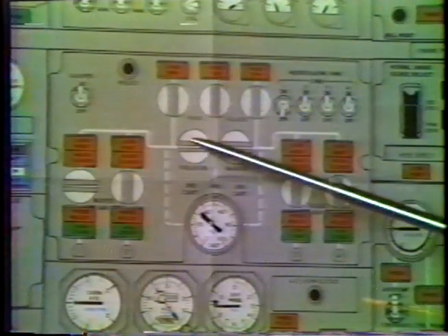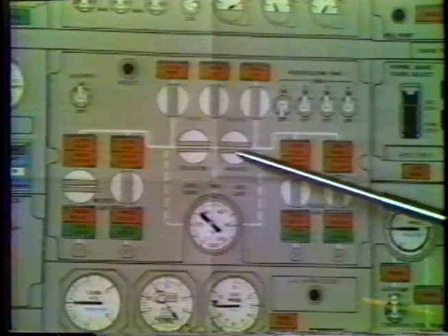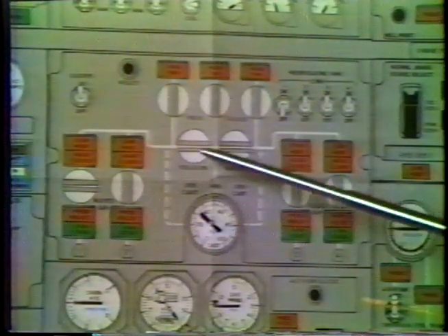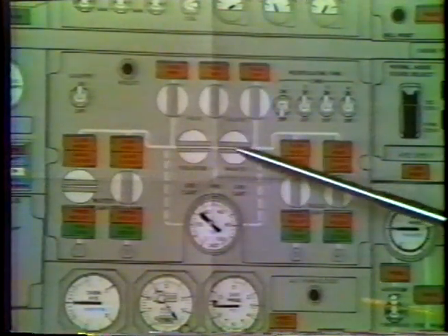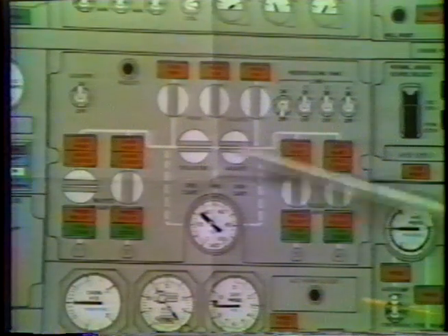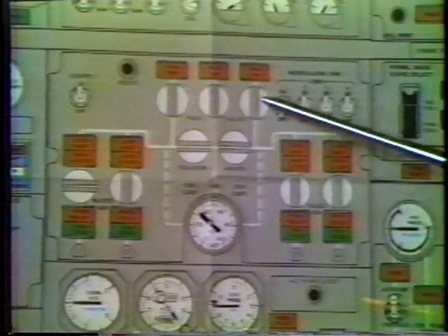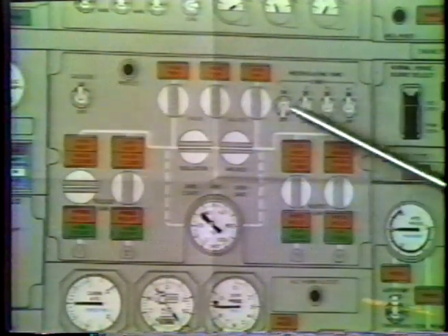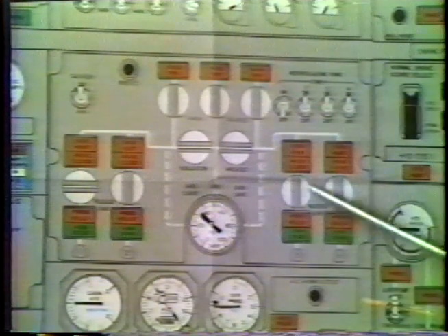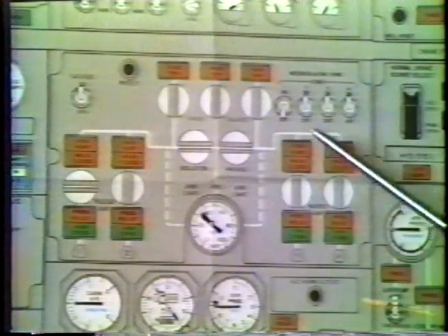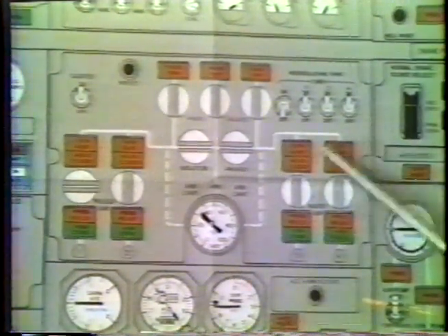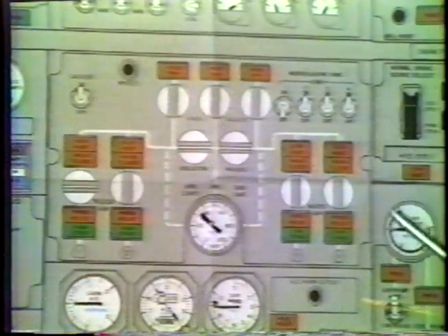We have 2 isolation valves, which cut the air out, going out to the wing on the left and right side of the belly of the airplane. And we have 3 pack shutoff valves. To get the whole system all together, I'd like to show you a little diagram and go through the items that are operated off this pneumatic system.